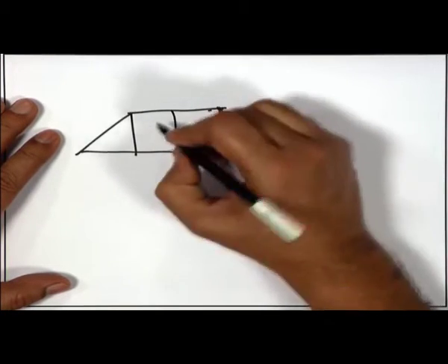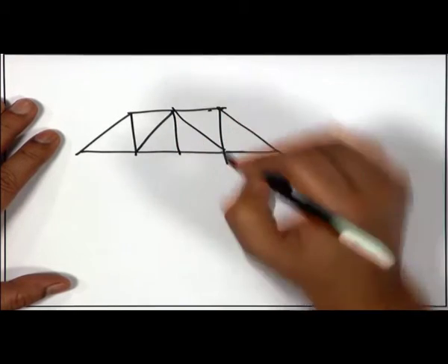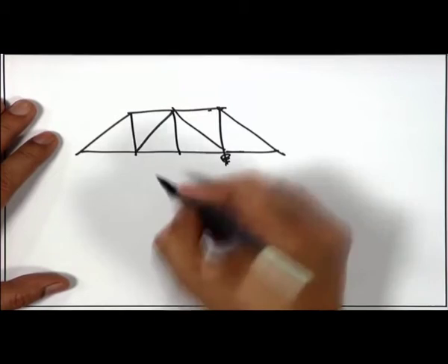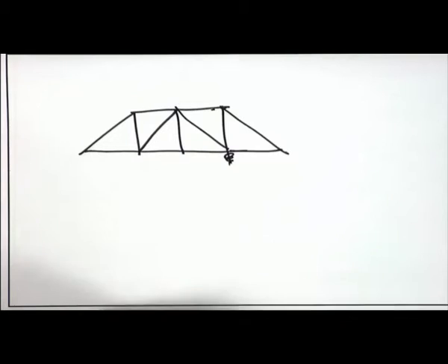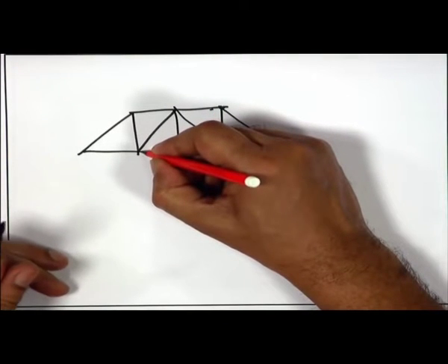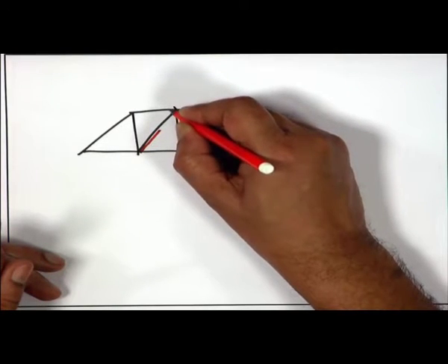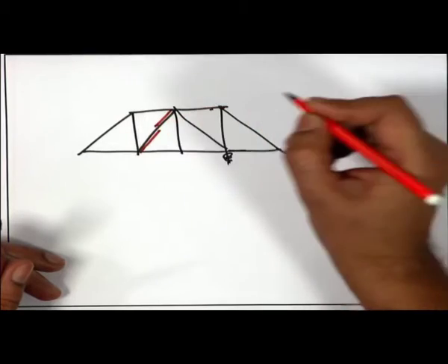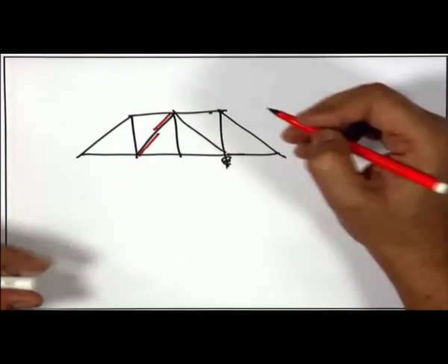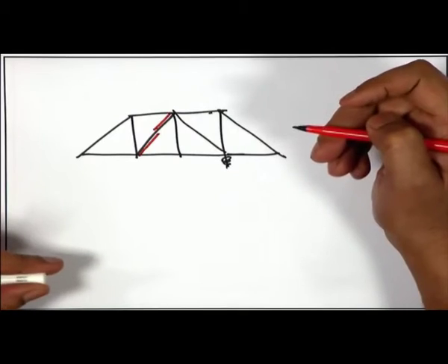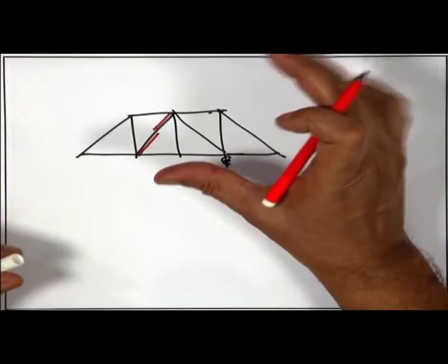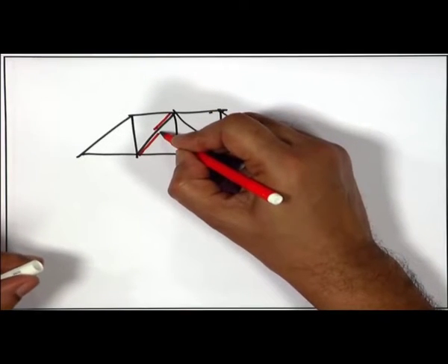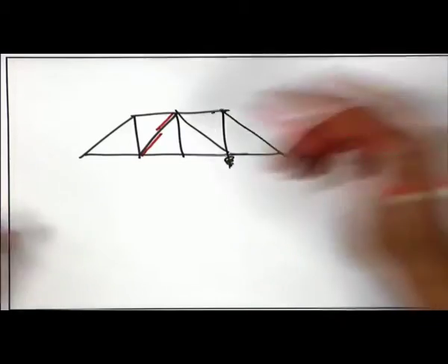So, what is there, yeah. So, this member. Okay. This is a statically determinate structure, unit load moves. Now, you see, if I am interested in drawing the influence line diagram for the axial force here, what should I do? According to Muller-Breslau, I should destroy the capability of resistance for the same stress resultant of the structure. If I am interested in the influence line diagram for the axial force, then I should destroy it here first. So, I have destroyed it. So, now it is a cut.